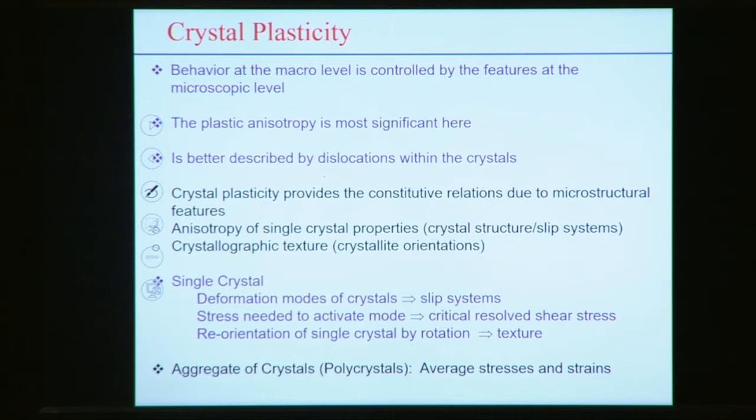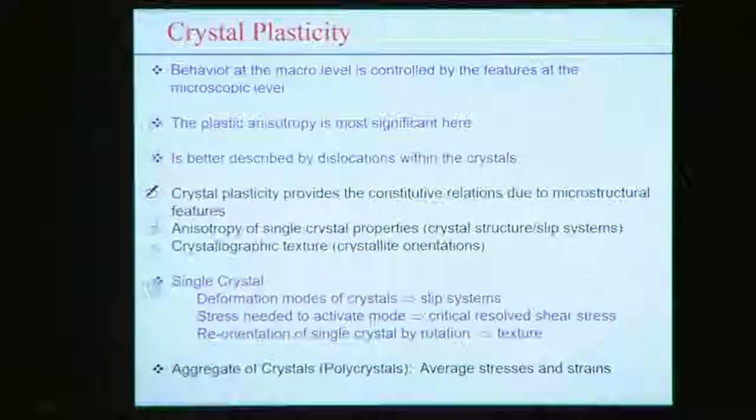Basically, shear stress induces the amount of shear strain, and that introduces slip within the crystal structure. And finally, reorientation of the single crystal by rotation. But aggregates of crystals, basically polycrystals, will try to explain all these things, averaging the stresses and strains to explain the plastic deformation of the material.